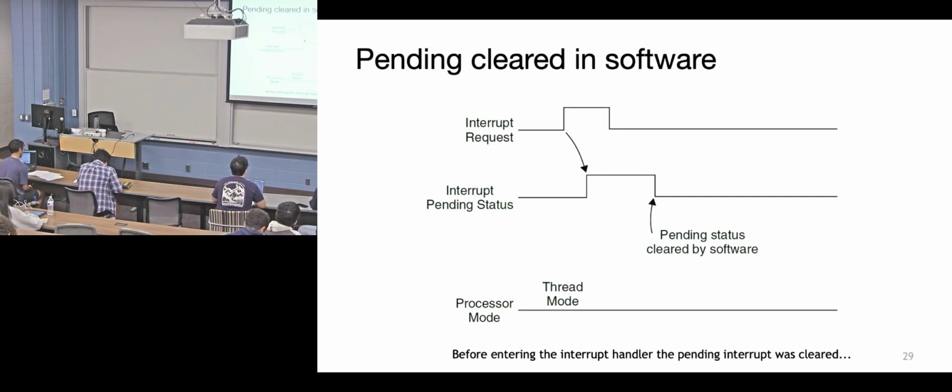This happens often, especially if you're changing your priority. So one thing that's useful is, if you're going to change your priority levels or enable an interrupt, you might want to clear it off first so you don't have a bunch of old pending interrupts going off. So it could be the case where you actually don't execute it if you clear it in software or some other mechanism. But that's just an edge case to explain.